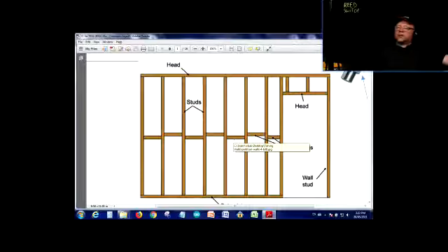If you don't drill straight, it involves a lot of skill and a little tiny bit of luck as well, because you're not looking at the drill bit. You're just going to make an opening on the bottom part, and you're going to try to drill through this horizontal stud while the drywall is on, so you're not seeing that. You're going to go by feel. Hopefully you're going to hit the middle of that stud or the nudging, so you can go through this wood, but not come out through the wall on the other side.